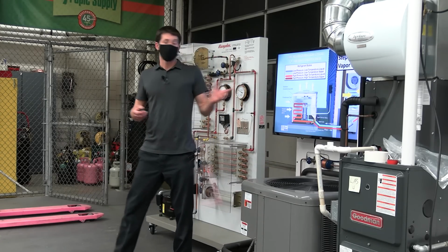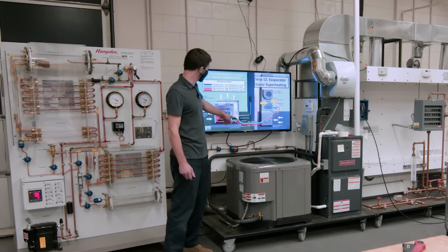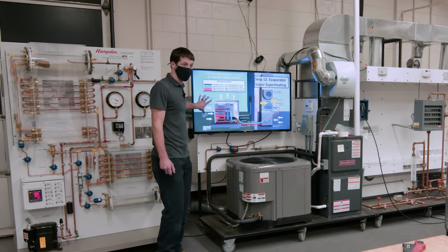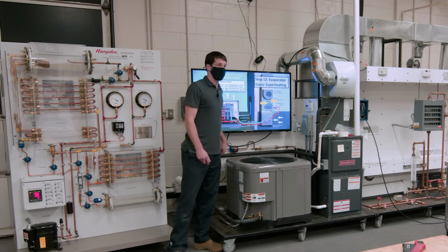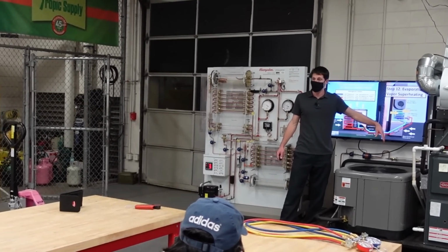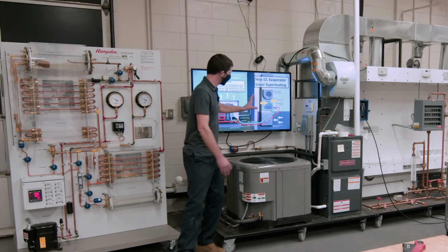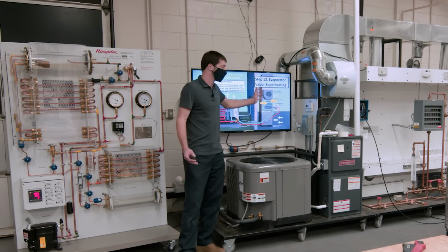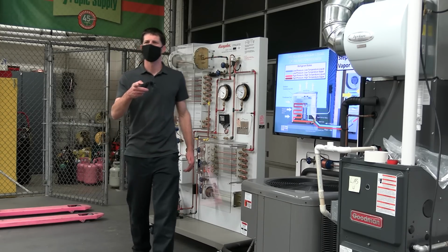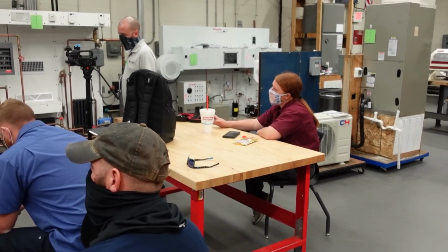But say it's 32 degrees, right? Or say it's 33 degrees saturated temperature here. And the day that you're checking it, it's like 100 degrees outside, and it's 76 degrees inside. That coil's going to freeze. Once the indoor temperature lowers, that coil's going to freeze. You still have a problem there. Something's not right. So the manufacturers are designing roughly the saturated temperature to be around 40 degrees, but it doesn't mean it's going to be that way. Anybody else have any questions? Well, that's just like the liquid line temperature cannot be lower than the ambient temperature.